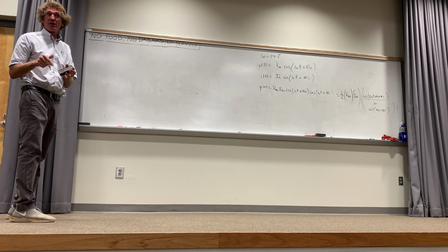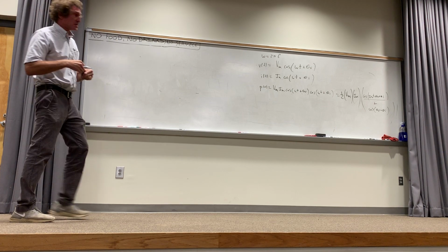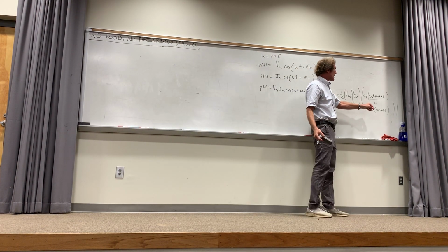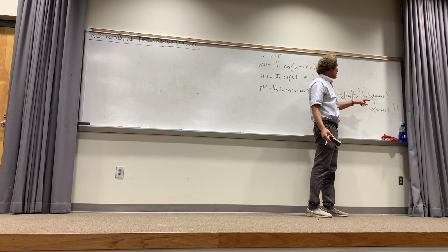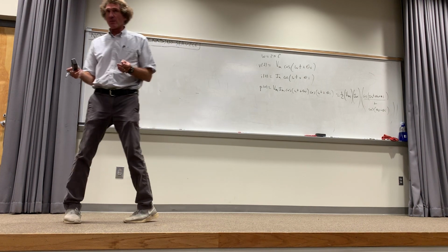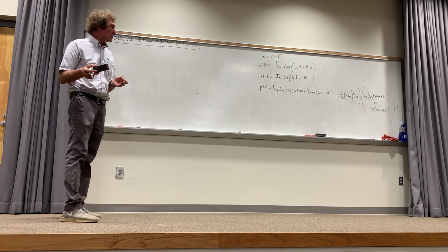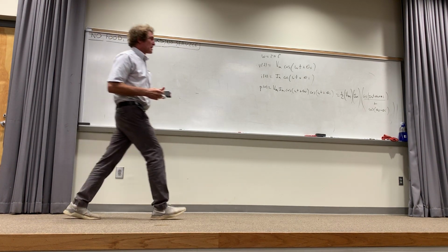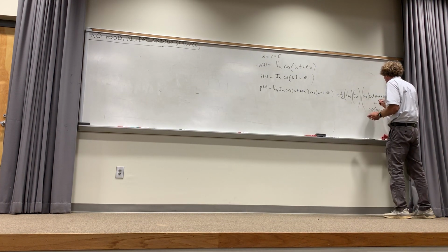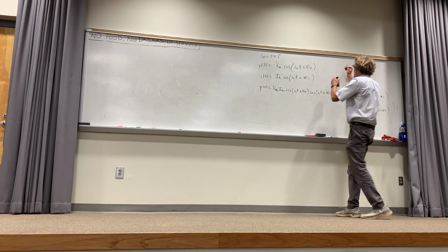Yes? So that p of t, that long equation, is that the instantaneous power? Yes, it is, and it's because it's a function of time. If you look here, you pick a time, you give me theta v, theta i, and Vm and Im, I can tell you what the power is in watts. It goes to 0 at some point, by the way. What's in the denominator of the last one? This is not a fraction. This is plus this.